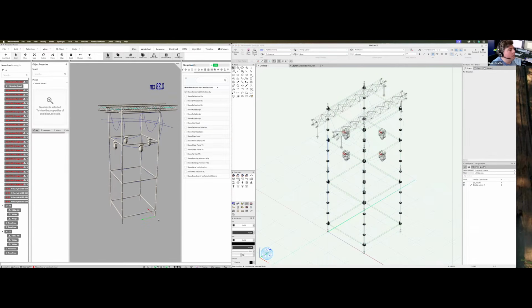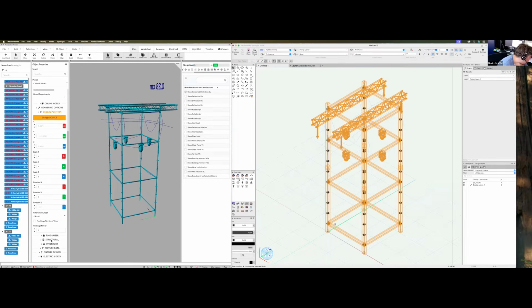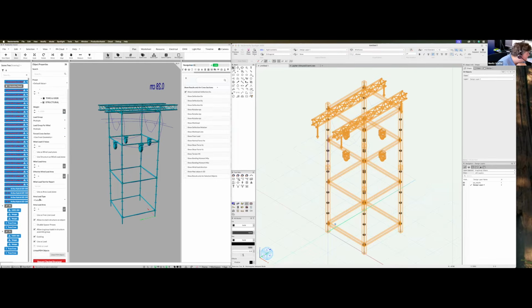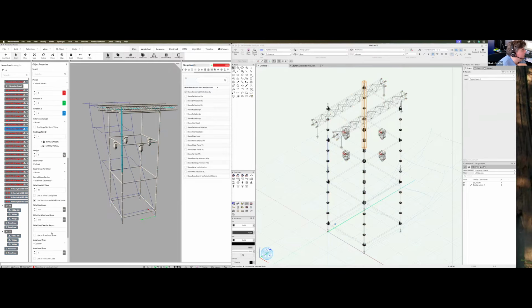There are multiple options to put wind loads into production assist. The easiest way is to select everything in here, where the layer scaffolding structure is not cluttered, so it's only the base structure. For this, there is a setting in the structure, use structure as a wind load plane. If you activate this, the internal cross-section knows how much wind it generates. If I activate this here, I can select this and you will see that it calculates the wind load area.